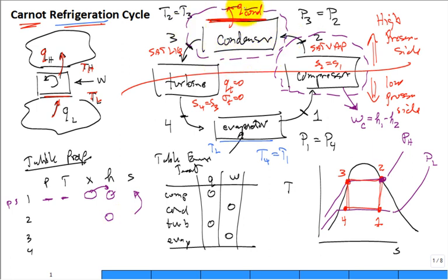And I know that I showed that positive condenser going out, but I'm going to switch it now. And so Q condenser going into my control volume surrounding the condenser. We know that's going to be negative because it's really heat rejection. But it's going to be the H3 minus the H2. H3 is lower than H2. I'll have a negative quantity, and I'll be able to calculate that.